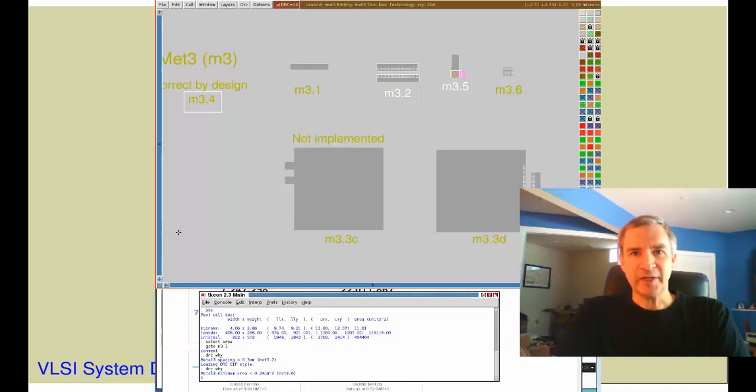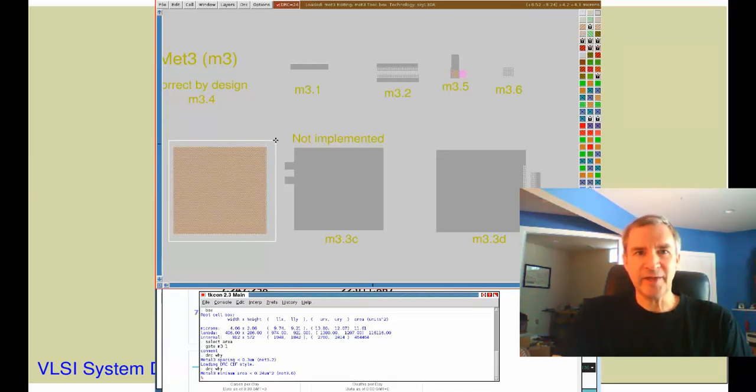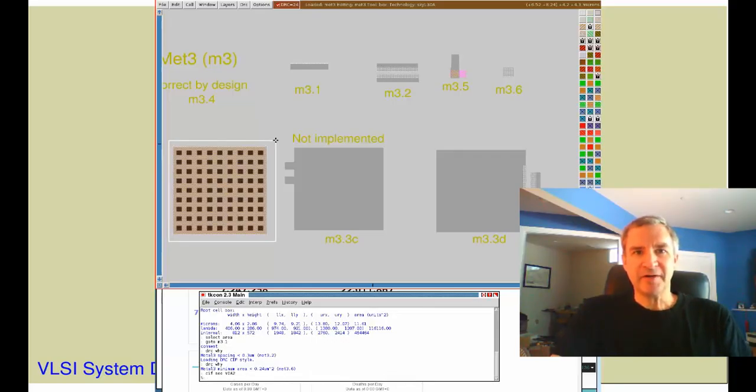To see that visually in the Magic layout window, draw a large area of M3 contact, which you can do with the paint command or by hovering the mouse pointer over the M3 contact icon on the sidebar and either clicking the middle mouse button or typing the P key. Then, with the cursor box still around the area you just drew, type the command sif c via2, with via2 in caps. You'll see a bunch of black squares appear inside the area.